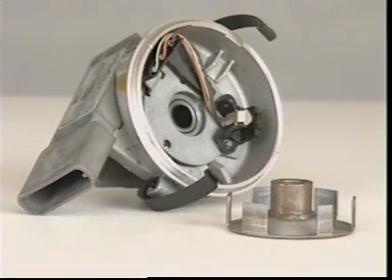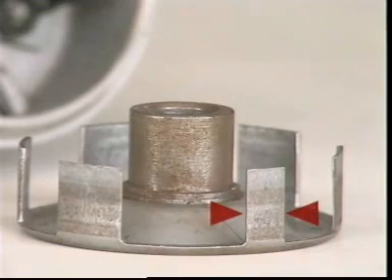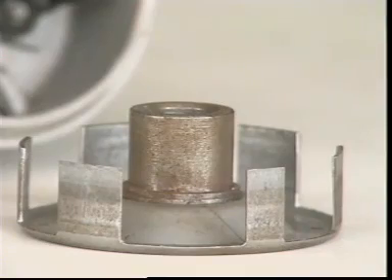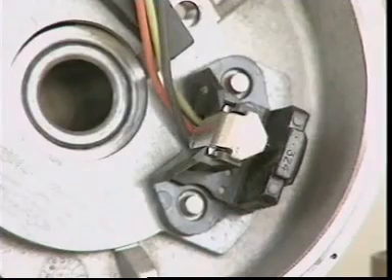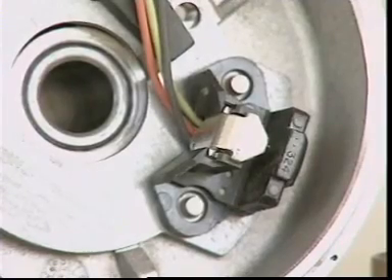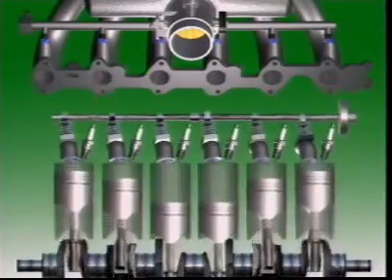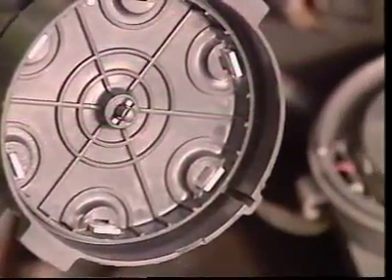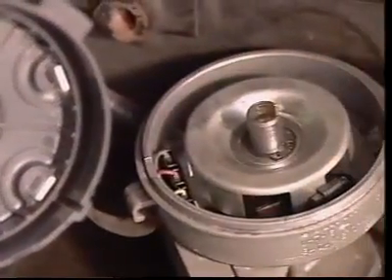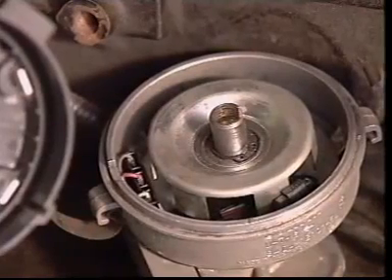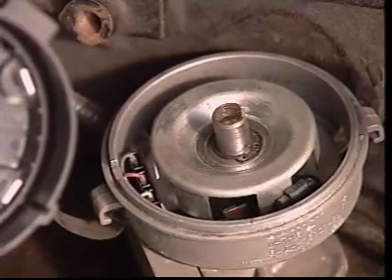If a sequential injection mode is used, the position of the camshaft must also be signaled to the control unit. This is done by making one blade of the interrupter ring shorter than the others. It's called a signature blade. It passes through the sensor and alters the signal, so that injection commences at the correct time in the cycle. Since the distributor rotates at camshaft speed, the sensor in the distributor provides camshaft position readily.